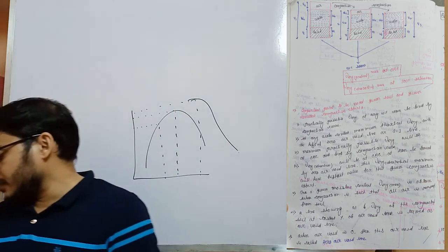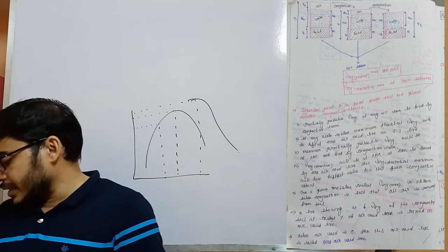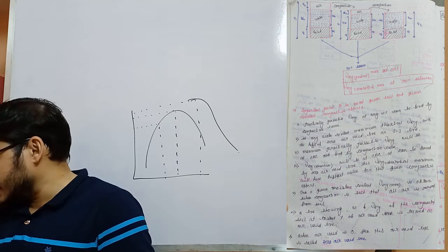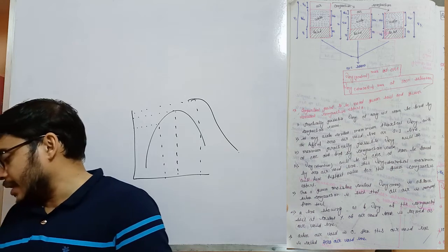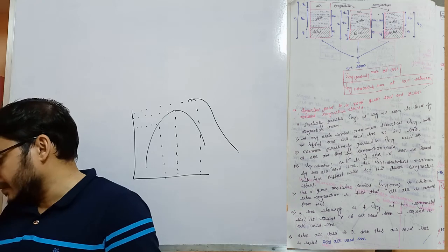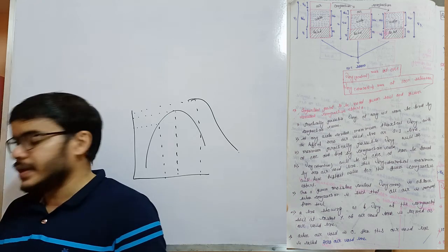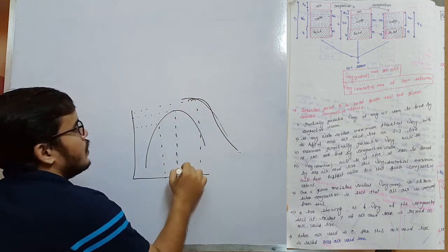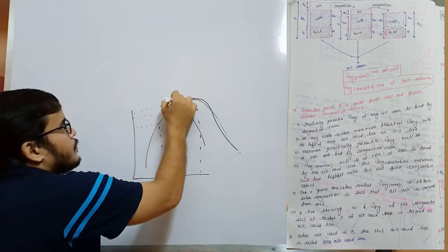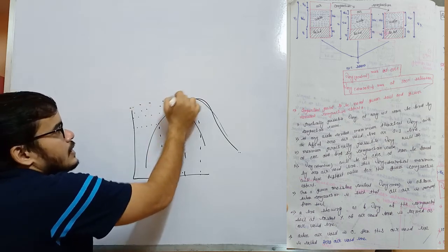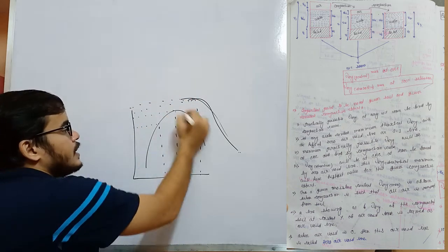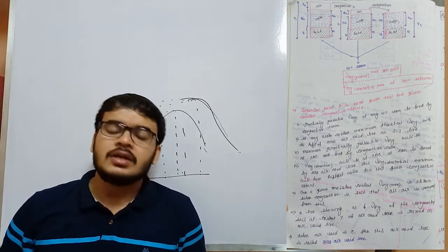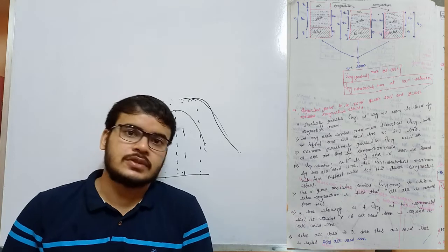And fourth point, gamma dry theoretical at OMC can be found by the zero air void line, and this theoretical maximum gamma dry will be the highest value for that given compacting effort. That means for this curve, at OMC we can get the maximum gamma dry value, and that will be theoretical, not practical, because practically it is impossible to remove all the air from the soil.